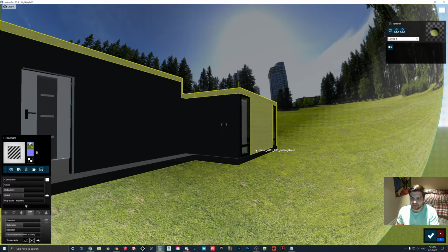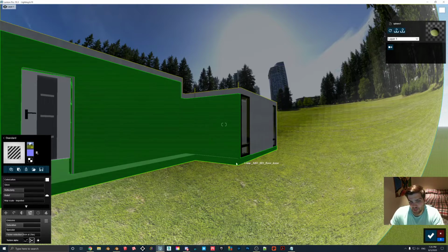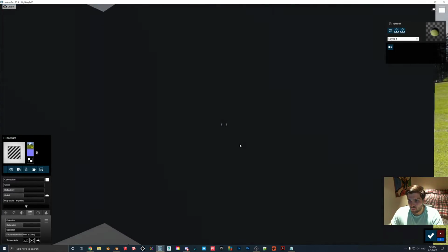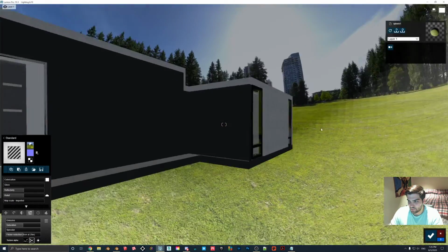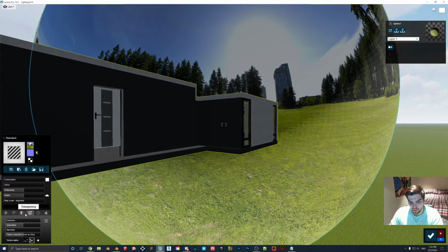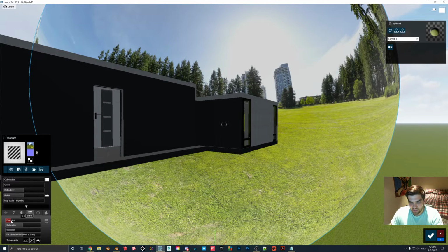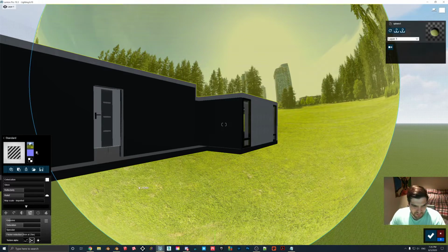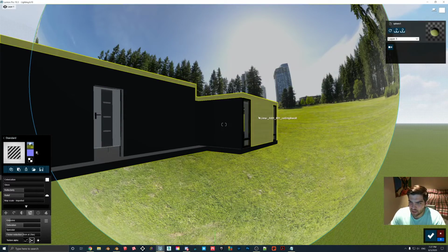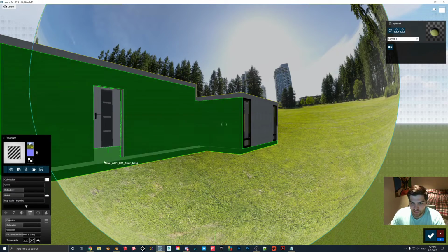And those fine details, like those pockets of dead mowed grass that you see on the lawn, I don't really know an easy way to do that in Lumion. You could make your own material, but it's just not worth the time when you can do it like this. So going in here, we need to bring it down a little bit. We'll go to emissive, and I like to bring it to right here for an afternoon day. When it's at 0.1, it really starts to give off its own light, and you don't want that. You just want to make sure that everything looks realistic.